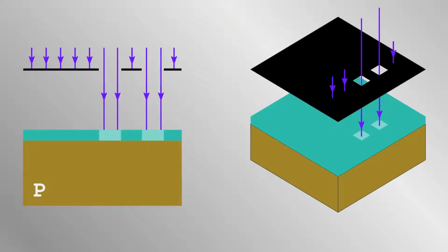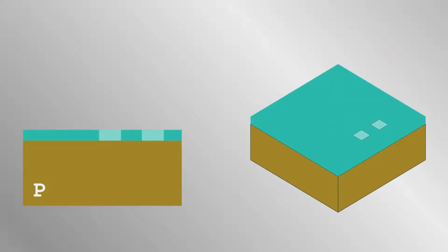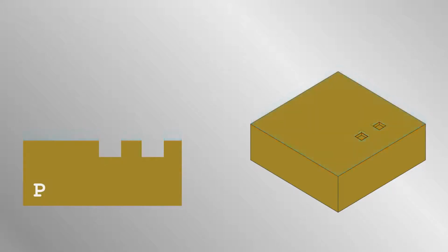The exposed areas must be the same size or larger than the wavelength of light used. Hence, very short wavelength ultraviolet light is used for lithography. A special etching method is used to remove only regions of photoresist which were exposed and nothing else. This opens up gaps in the photoresist, and then another etching method is used which targets everything except the unexposed photoresist. Finally, the remaining photoresist is etched away. As a result, material has been removed wherever there are any gaps in the mask.